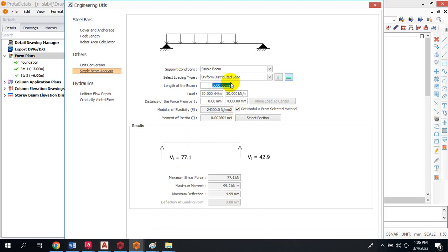Okay, nice. You can see the value here is giving us a different result because this is not loaded uniformly on the entire span. When it is loaded uniformly on the entire span, it gives you back that same result we got. If you are loading it from this span to 4 meters, for example, the value is also going to change. If you solve this manually, you are going to get the same result gotten here. So whichever way you load this particular member, if you solve this manually, this is exactly what you are going to get, with no difference at all.